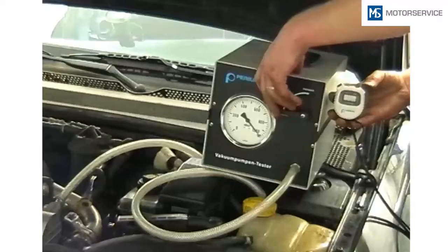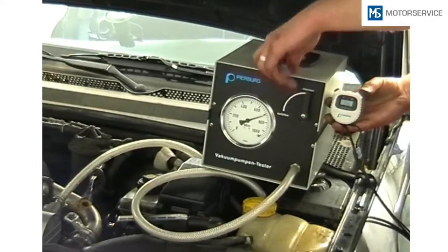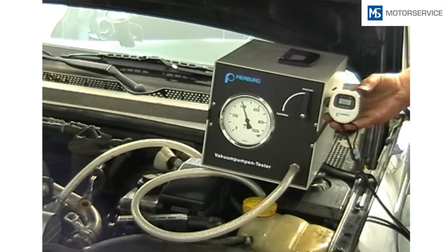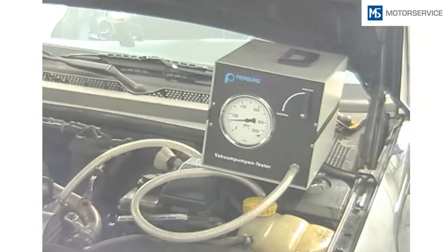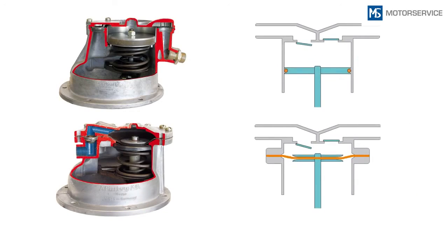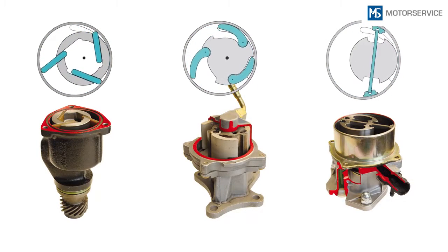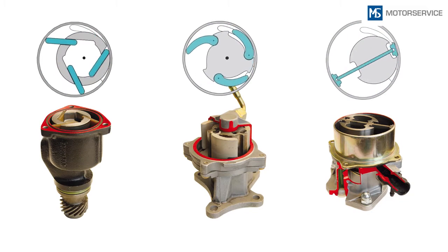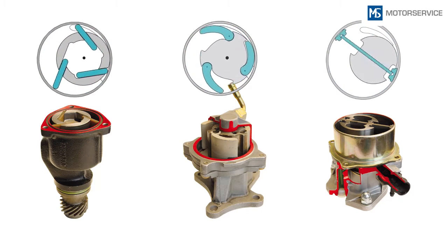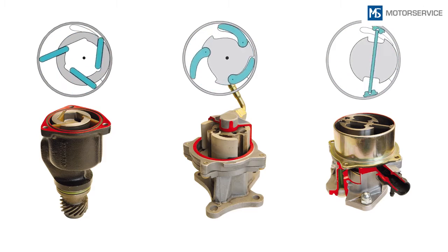Vacuum pumps, as used in motor vehicles, produce a vacuum of approximately 0.7 to 0.9 bar. They must be designed to ensure that sufficient vacuum is available for the brake booster even with frequent braking maneuvers. Vacuum pumps that move a piston or diaphragm back and forth have long proven their worth in the field. A more recent development is vane vacuum pumps with rotary drive. Here, a rotor with one or more vanes forms compartments, the size of which varies during the work cycle.